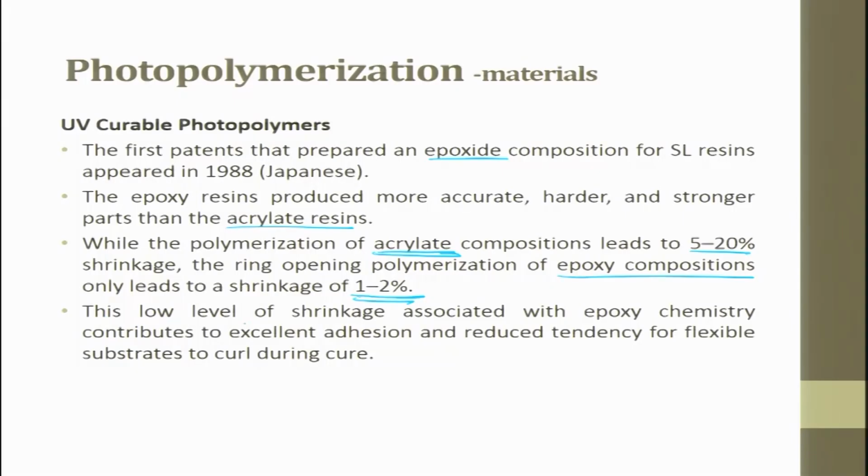This low level of shrinkage associated with epoxy chemistry contributes to excellent adhesion and reduced tendency for flexible substrates to curl during curing. So, this epoxy chemistry made a big change in photopolymerization, which is the principle used in the stereolithography process.